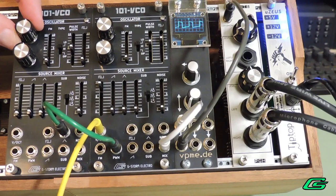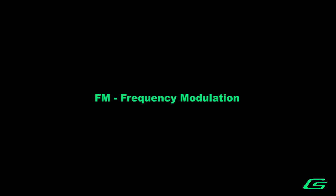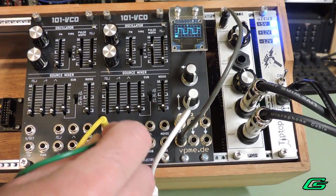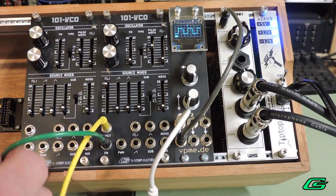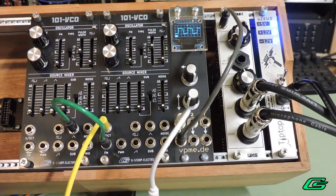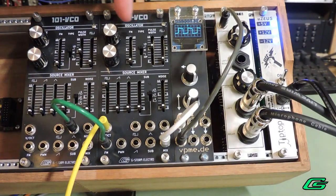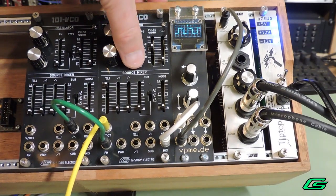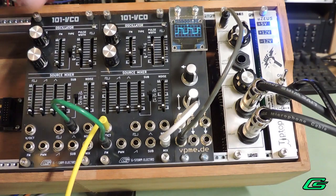Keeping this configuration of using another VCO to control the first VCO, supposing we wanted to modulate the frequency of the first VCO, there's an FM input jack just for that. Frequency modulation. Over here are the mode and amount controls for that. We have different FM modes because they all offer a different flavor. The low mode will allow us to make a vibrato.